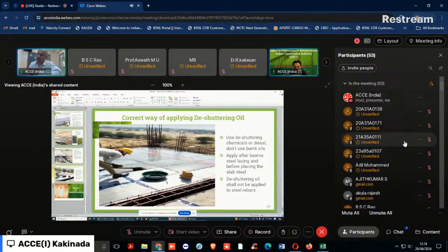For this, you require better gripping between the concrete and the steel reinforcement. For that, we are using the modern-day TMT bars, which have much higher lugs when compared to the previous TMT bars. Some manufacturers are manufacturing with extra ribs also for better gripping. And this gripping, with respect to the adhesion, the chemical and mechanical bonding between the concrete and the steel, plays an important role in transmitting the tensile stresses from the concrete to the steel. The tensile stresses primarily come from the concrete, and they will be transferred to the steel through proper bonding, that is the strain compatibility.